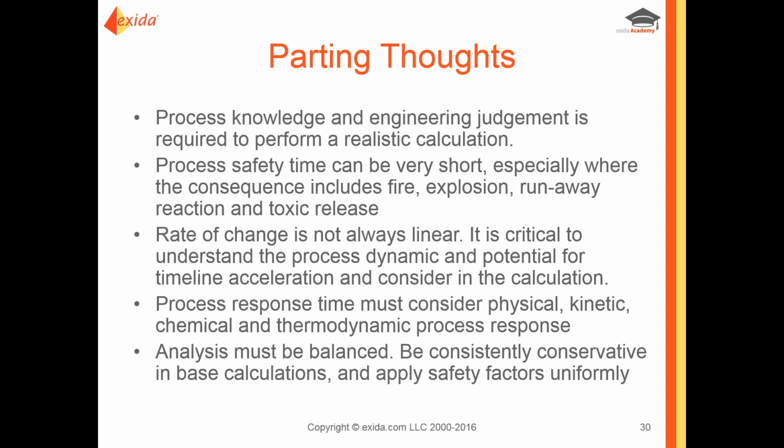You must understand the process dynamics. In something like a runaway reaction, the timeline can actually accelerate in an exponential manner. So you have to work off of full information, because just taking the very beginning rate of change could very seriously underrate the process safety time, or under-calculate it, as the process excursion rate escalates towards the end.